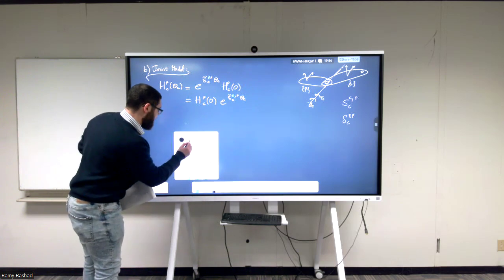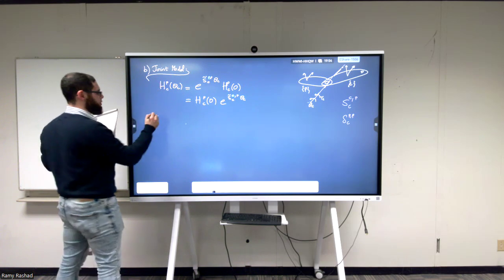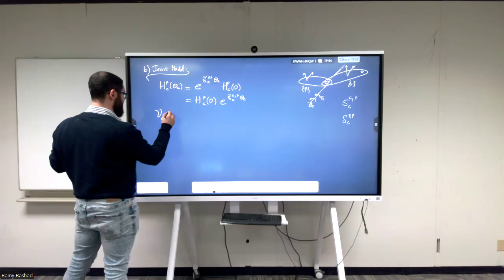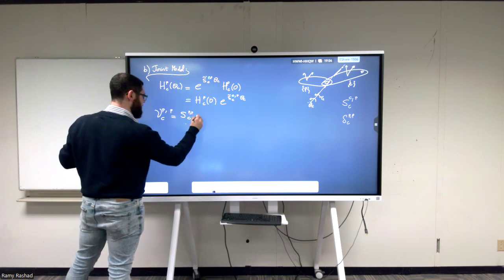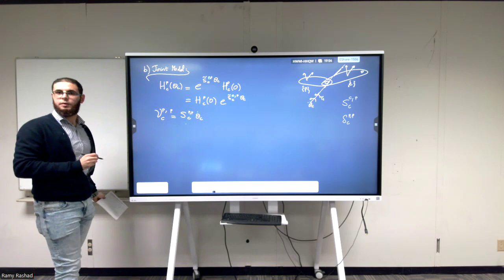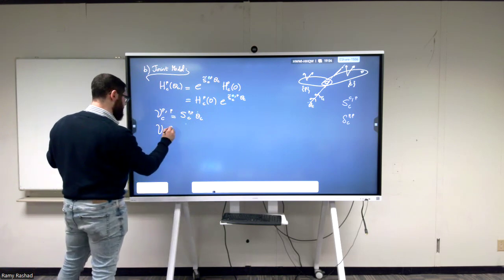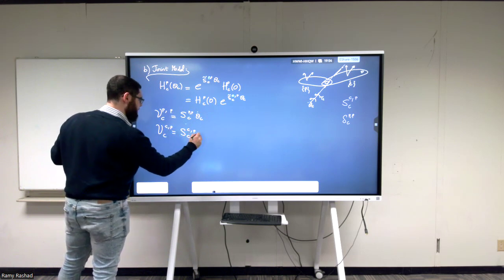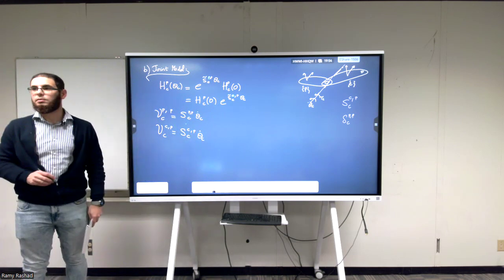What about the twist and the relation to the angular velocity, which is theta dot? If you talk about the relative twist between C and P expressed in the P frame, then it's simply S_CP in P multiplied by theta_C dot. If you talk about V_CP in the C frame, then it's equal to S_PC multiplied by theta_C dot. It's as easy as this.